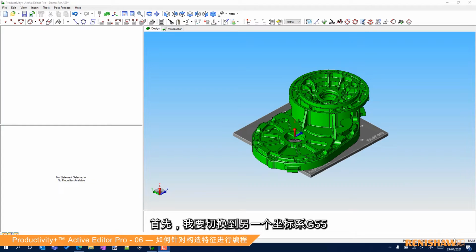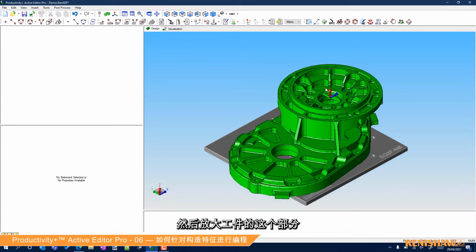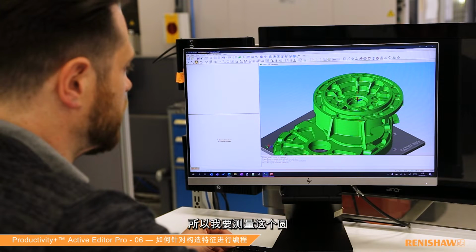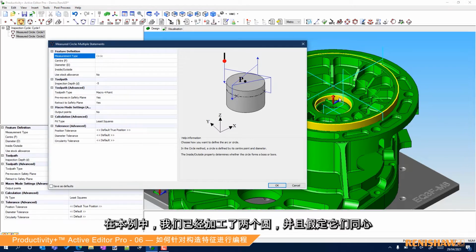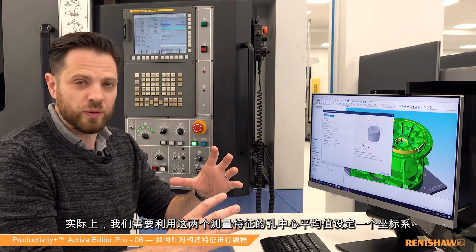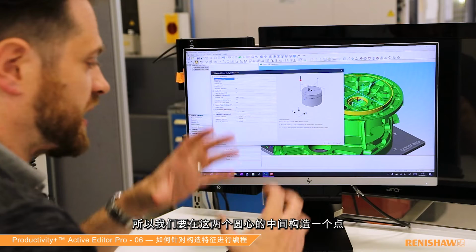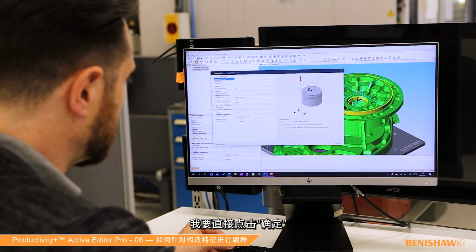So what we'll do first off, I'm just going to switch over to our other coordinate system, our G55, and zoom in onto this area of the part. And I'm going to measure a couple of bores. So I'm going to measure this circle here, and I'm also going to click and measure one of these internal ones. So the example here is where we've got two machined circles that are supposed to be concentric, and actually we want to set a coordinate system between the average of those two measured features. So we're going to construct a point that runs through the middle of those. So I'm just going to hit OK.